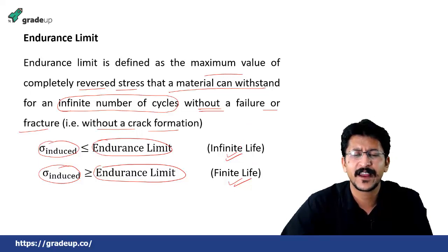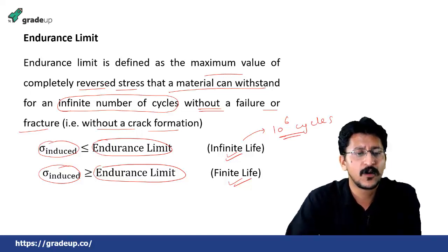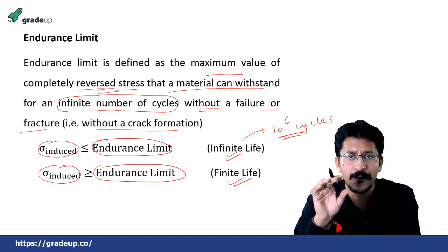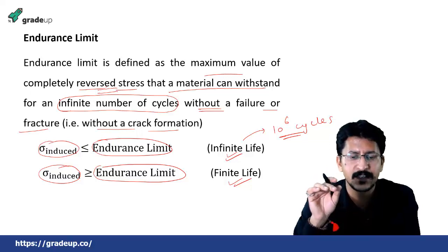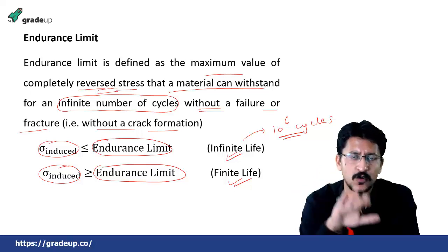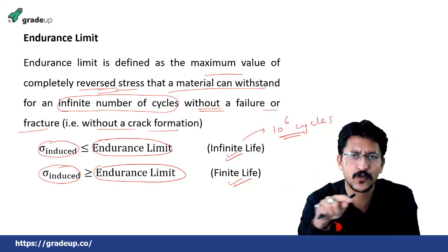And what is that infinite or finite life? It is basically 10 to the power 6 cycles, because it is said about the completely reversed stress. Changing the magnitude of load from one maximum value to another maximum value in the opposite direction constitutes one cycle.